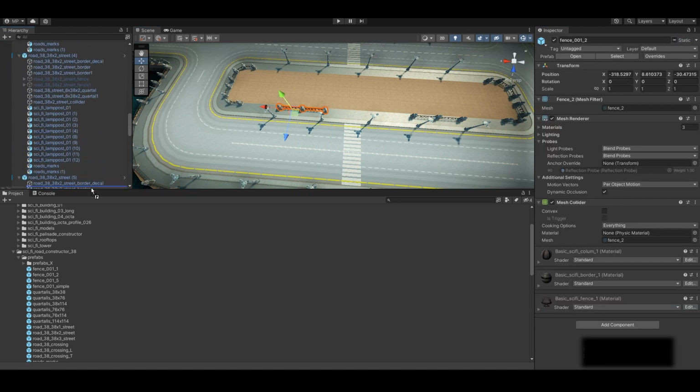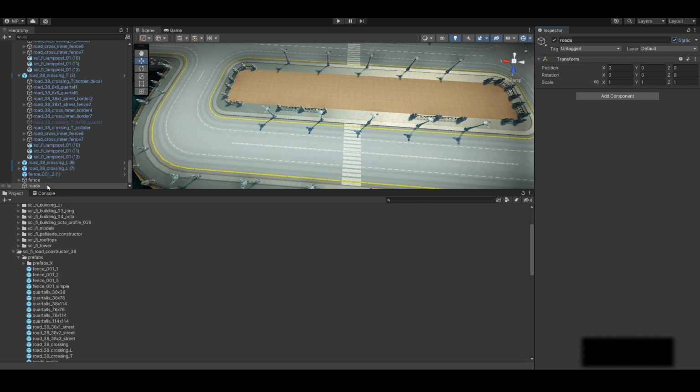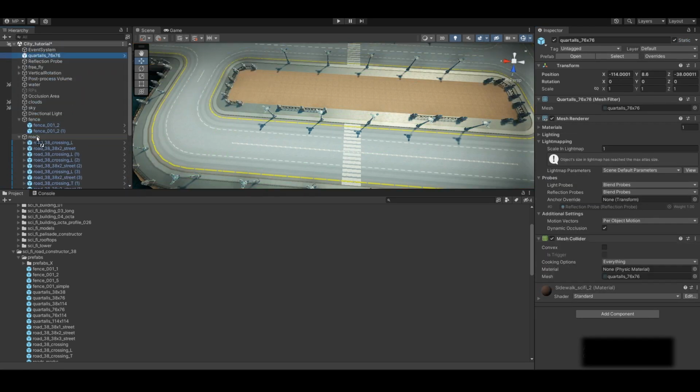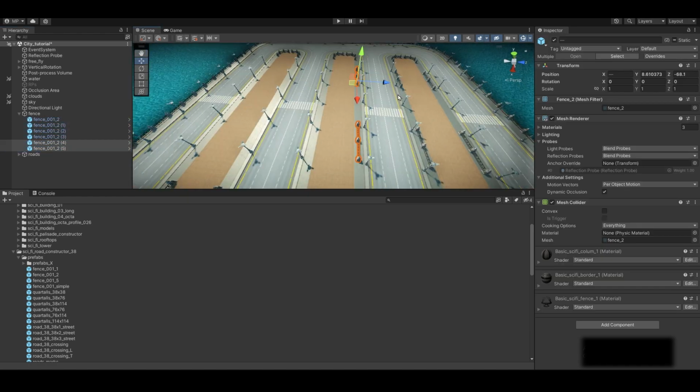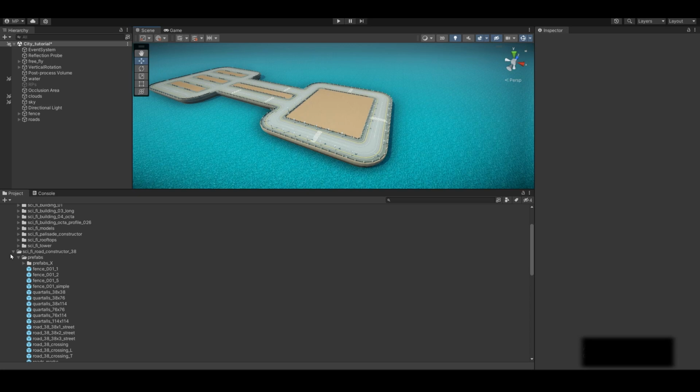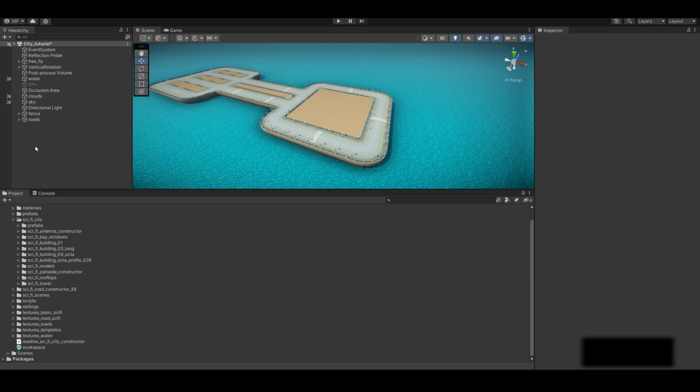Since there are a lot of prefabs in the scene, let's group them by type. Each time I create a new node in the group, I put a checkmark, static. This will allow us to not have to transform each frame at runtime, which will allow us to reuse large blocks from the prefabs in the future.